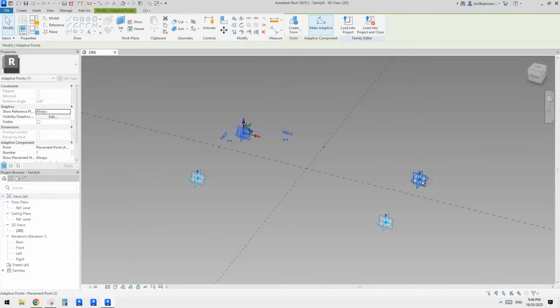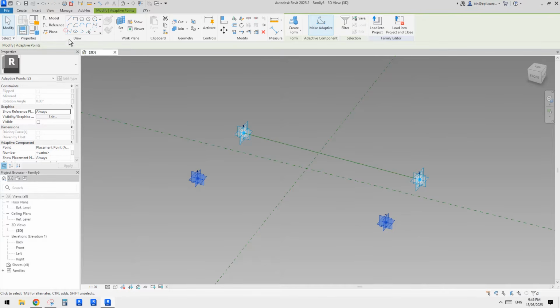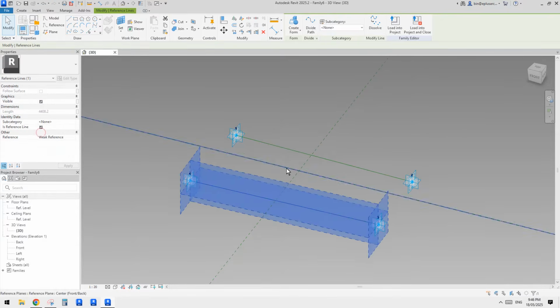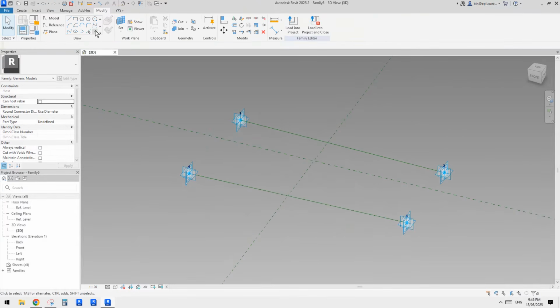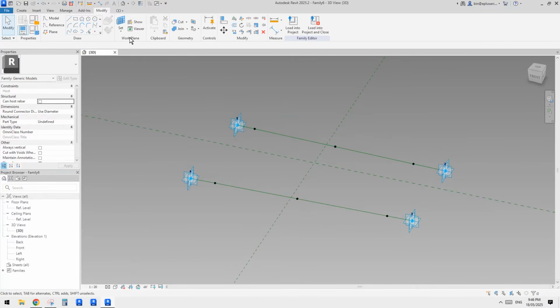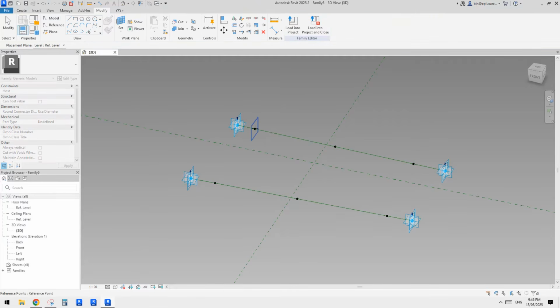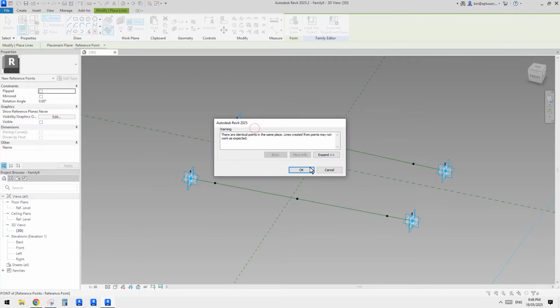Okay, so first we need to place a spline through points through these 2 points, and another one. Make them reference lines, and then place a point. Use draw on face onto. So actually, let's place 6 for now. Okay, and then we're going to place another point. Use draw on work plane, set work plane. So place onto the horizontal, so tab, and place onto the point.